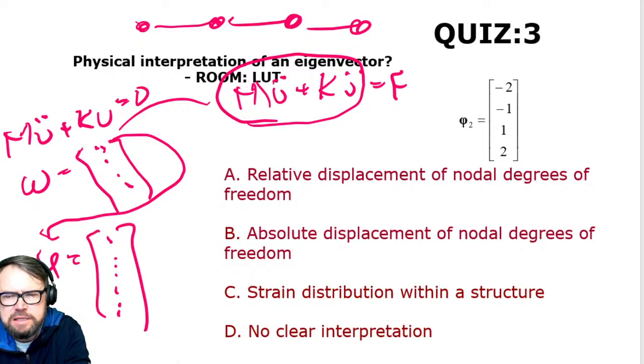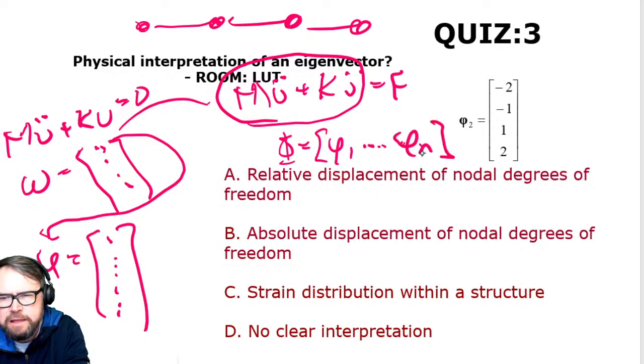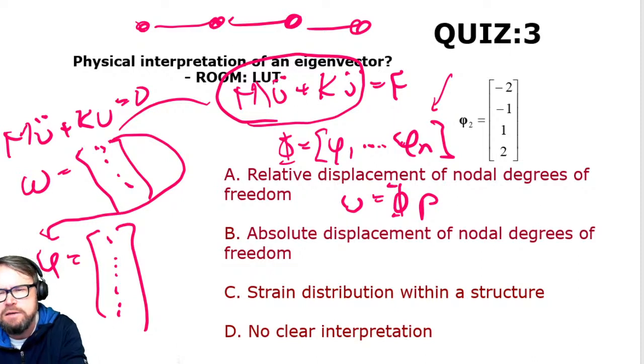All right. Then what I can do is build a matrix from these deformation modes. So this is the first one, and this is N1. This one here allows me to find the relation between nodal coordinates and modal coordinates. This MP here, there will be an equal number of P's and there will be these modes. And they are telling me how much one deformation mode is contributing to the final response. That's what I wanted to do.